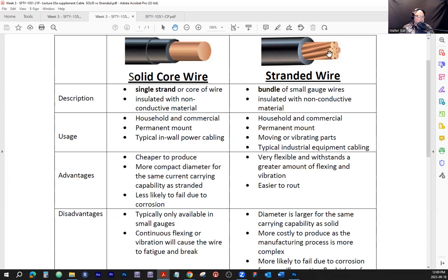That's why when you have wire strippers, you have two grooves for each gauge. The stuff that we use is mostly gauge 14, so you're going to have a groove that says 14 solid and 14 stranded on your strippers. And of course, the stranded groove is going to be slightly bigger.